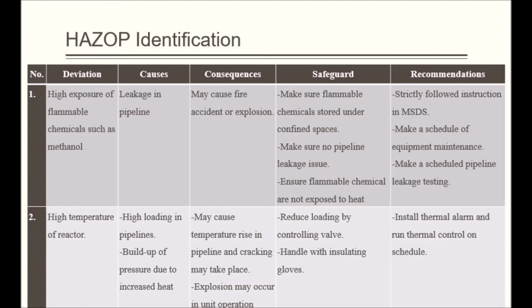Next, high temperature of reactor may cause high loading in pipeline and build up of pressure due to increased heat. The consequences of this deviation may cause temperature rise in pipeline and cracking may take place.